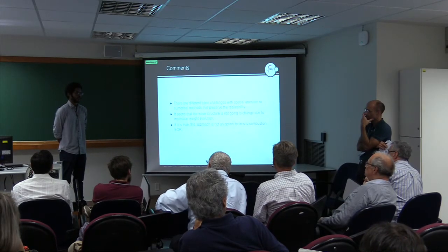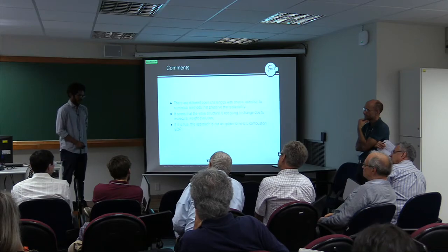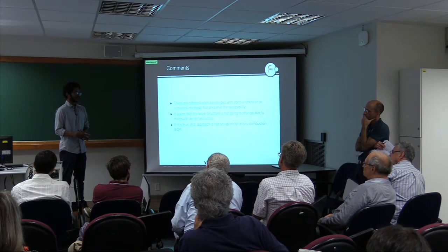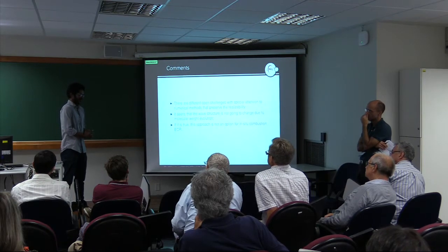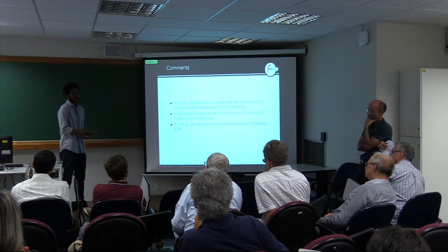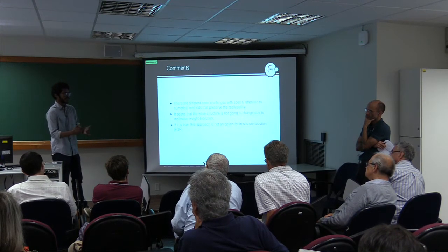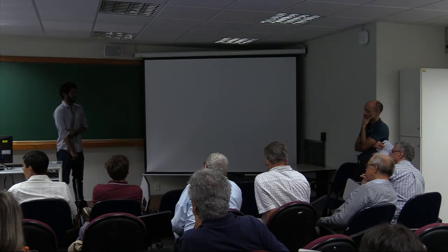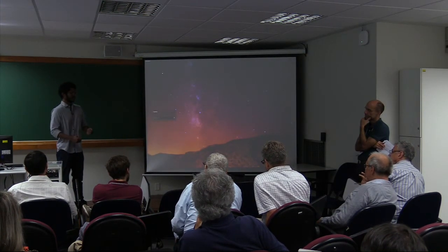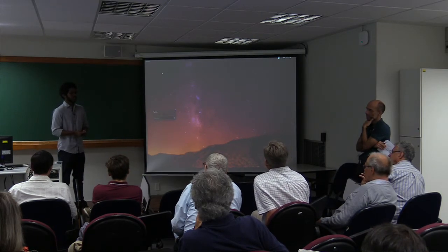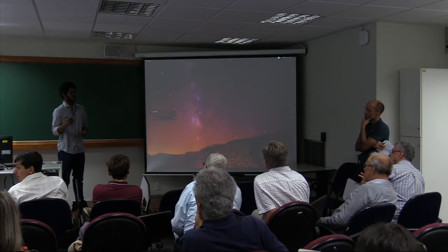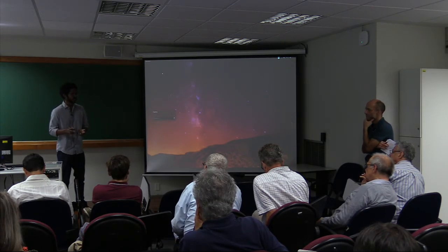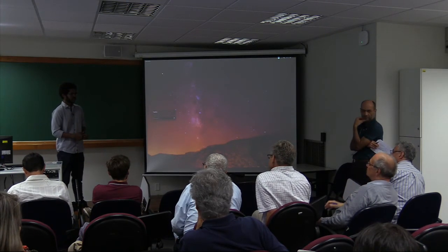Because when I have a complex oil, and we have a process where vaporization and reactions occur, the composition changes along the way. When I use moments, I can conserve the molecular weight, and molecular weight moves during this transformation process. That's why I try to use moments instead of discretizing. It's like an adaptive way to calculate quadrature points. With fixed quadrature points, engineers are used to fixing the points and calculating. In this case, we calculate the moments and move the points of quadrature, on a continuous curve.